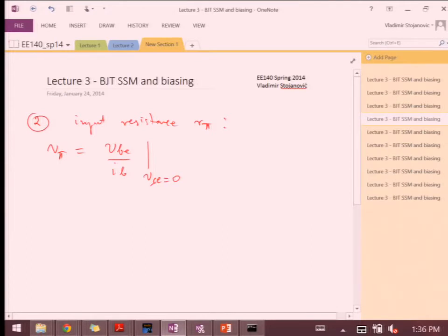That's just so I kill that other reverse path in case it weakly exists, right? So again here, because these are small signal, this is just a change in the true VBE over I base, subject to VCE equals constant. So I don't want any effects from modulating that bias junction. And we'll see later where that actually comes into play.